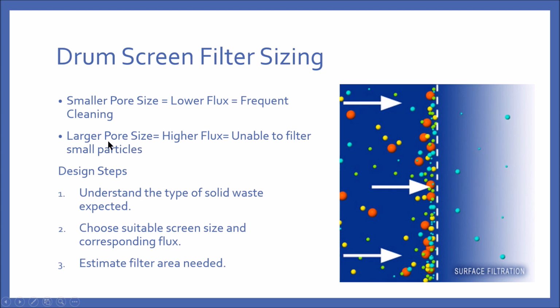However, a larger pore size will give you a higher flux, but you are not able to filter small particles. So understanding the type of solid that is expected in the system is important, as it will determine your pore size, which will give you the corresponding flux, and from there you will estimate how much filter you need.